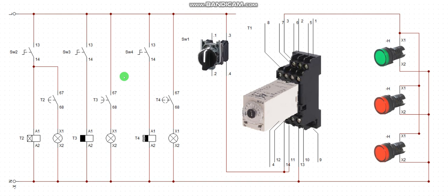But now that same function can be downloaded into the PLC. Write that same code in the PLC, telling the PLC to put on generator 1 for some time, shut it down, put on generator 2 for some time, depending on whatever you want the PLC to control. So if you want to go into automation, you must come from a control perspective, because you must write your code in the PLC according to what you want to drive.